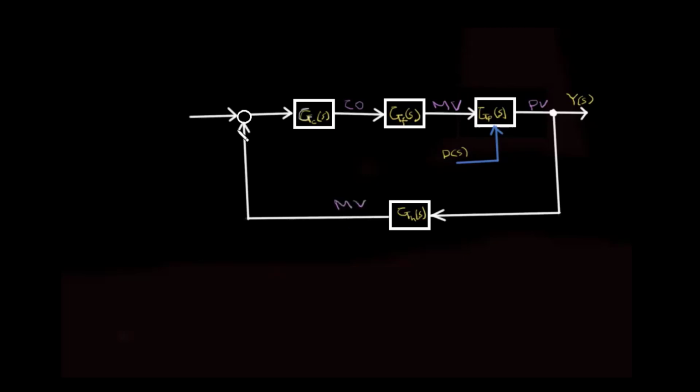This is going to be compared here with the input or set point, which produces the output, which is the error. So as you can see from here, the error equals the set point, or system input, or desired input, minus the measured variable. So in short, the controller compares the set point and the measured variable, and calculates a corrective signal which goes to the actuator. Then the actuator converts this signal into physical action which goes to the plant.